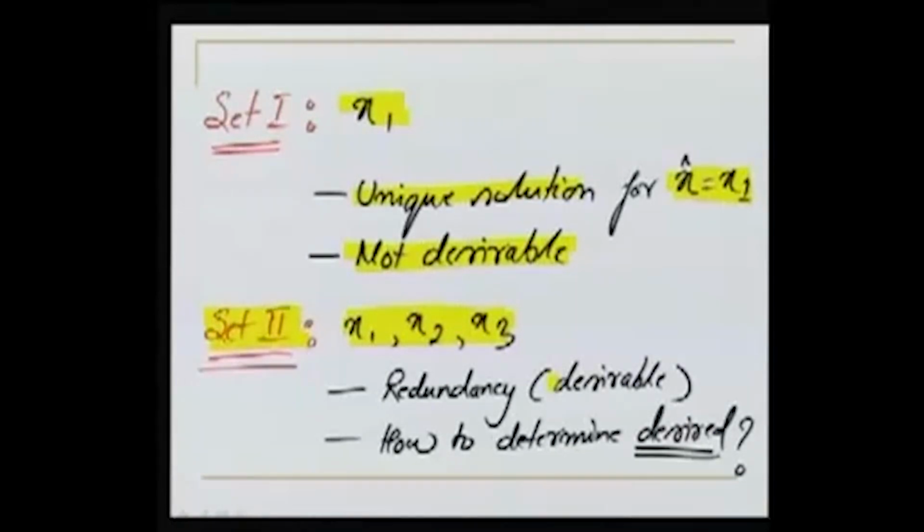Now this is very much desirable, because if in x3 there is some error, the chances are in x1 and x2 the error will be less. The errors are always there, but we have a way to check for huge amounts of errors, as well as we are carrying out multiple observations, so that we have more set of data. The redundancy is there, and this redundancy is very much desirable whenever we do surveying or any observation.